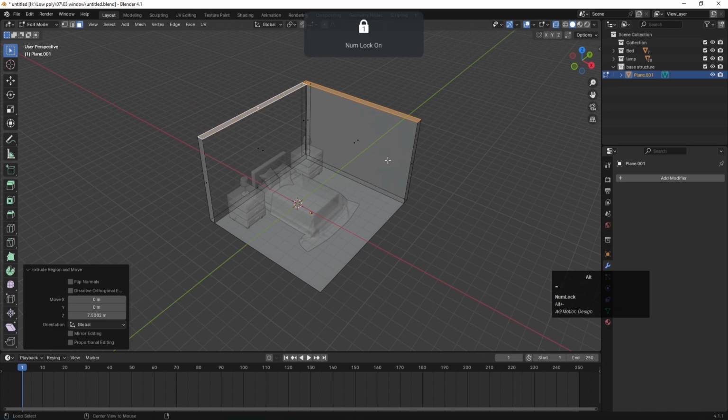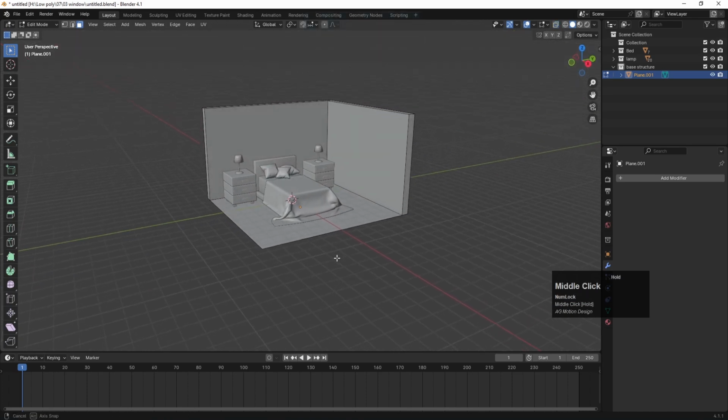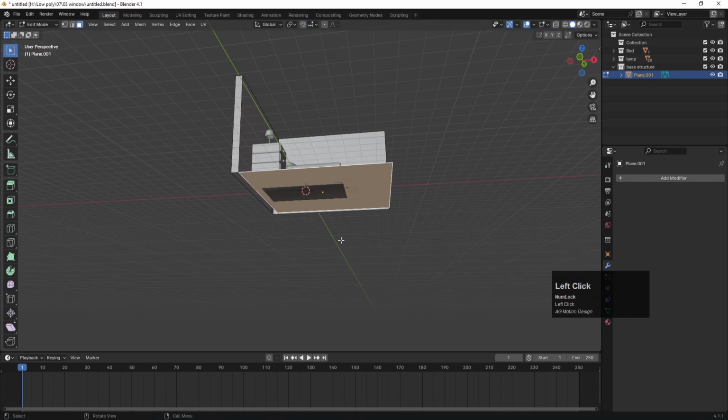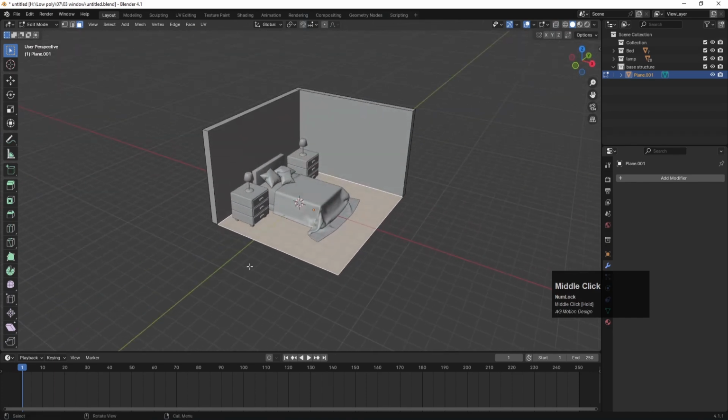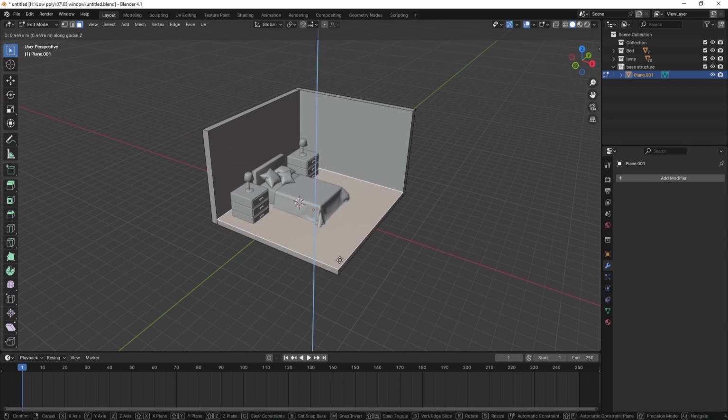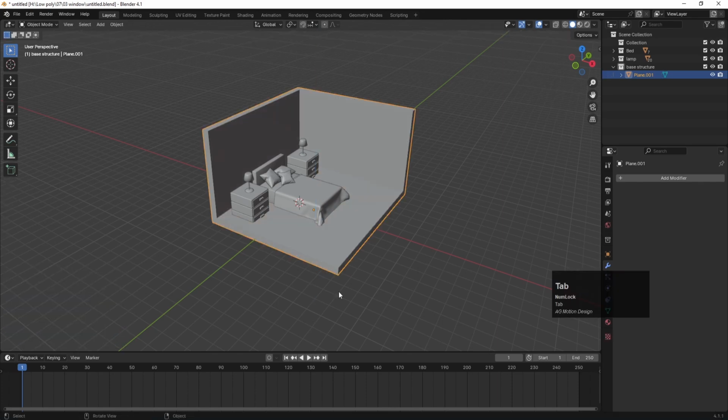Okay, I think this much looks good. Hold Alt Z and we will get something like this. Similarly, where I don't need to do anything for this side, but if you want, you can select this, press E and Z and try to bring this downward, or let's say bring this upward a little bit over here like this much. Okay, and press tab.